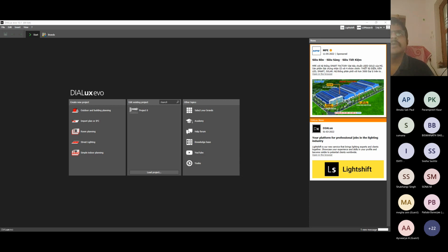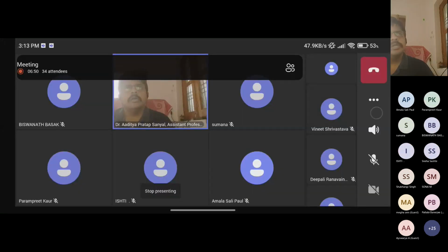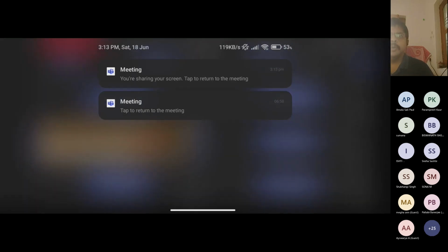Now there is a certain difference. Whenever we talk about these energy simulation softwares, you would also see that they have some sort of interface for lighting simulation, for both natural and artificial lighting. In terms of daylighting simulation, those energy simulation softwares are quite good because they incorporate most of the new practices, the LEED practices, such as UDI and SDA, spatial daylight autonomy. Whereas many of these lighting simulation softwares do not go too much into the daylighting aspect. They are mostly developed for artificial lighting, because that is what they cater to.